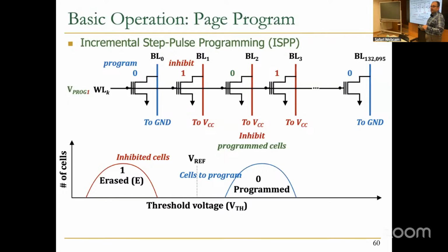Is this after the storage is aged? Or is it... No, actually, from the very, very beginning you need to do that. Just quickly, are these also destructive reads? No, it's not a destructive read. Destructive in the meaning of DRAM, that when you're reading, no, it's not that. But when you read, you might have some read disturbance similar to DRAM, and also write disturbance you might have.